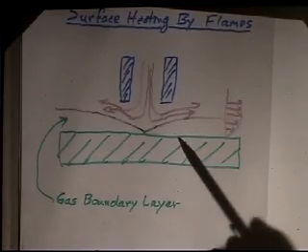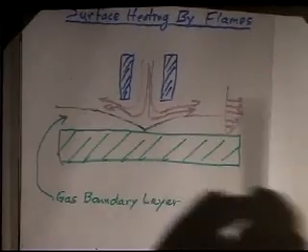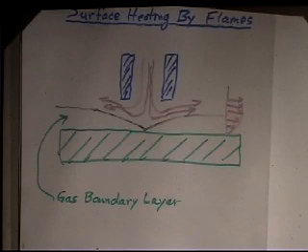Flames are only 2 to 10% efficient. Most of the heat goes off to heat up the surroundings in the air, not heating up the workpiece. You're basically heating up the welder, the person doing the welding, as opposed to heating up the workpiece that you want to heat up. So the gas boundary layer, which we will get back to when we talk about cutting technology, the gas boundary layer is the major problem.